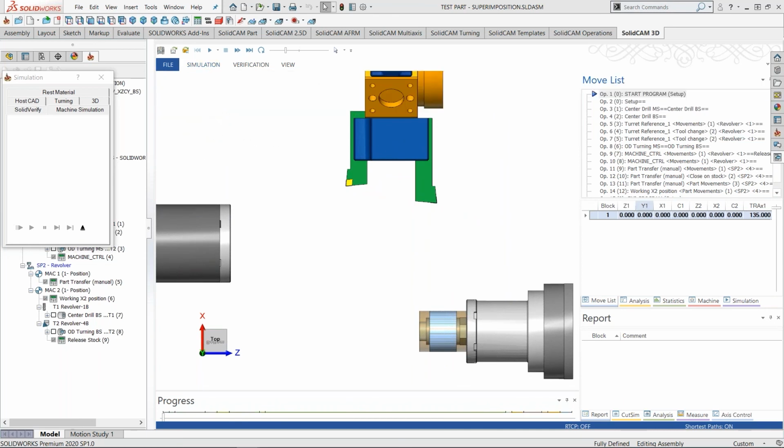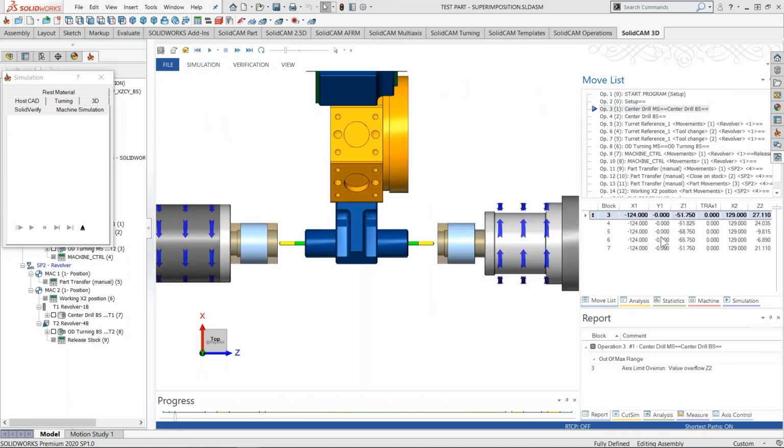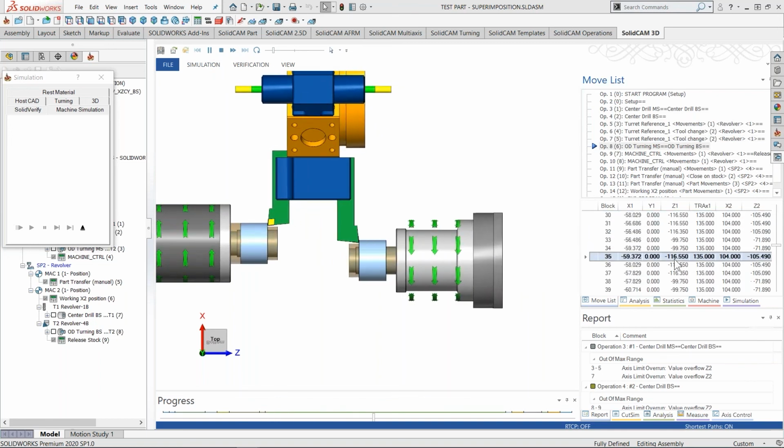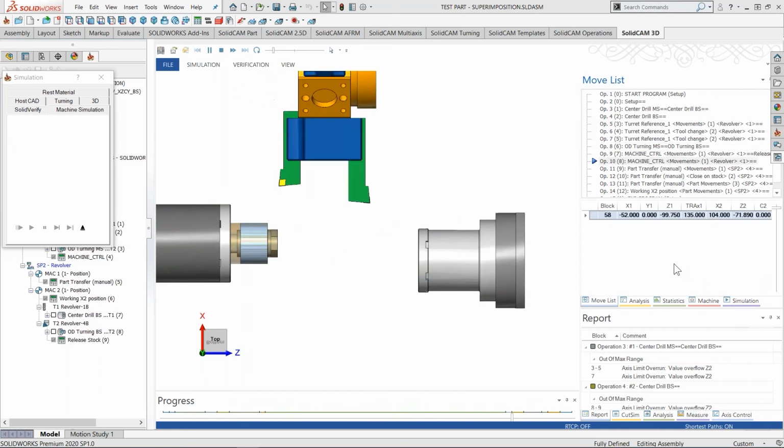If you go to the NC mode, basically what you will be able to see is just straight lines from each of the blocks. That's why you can sometimes see the simulation is pretty choppy. So probably, Mikhail, this is the reason why you see this simulation. If I run it right now, you will see that it's very choppy because it runs each code with very straight, sharp lines.